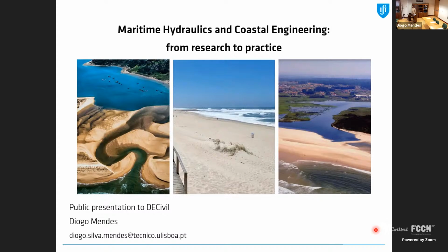Another thing is that you were showing two lagoons, the Albufeira Lagoon and the Barrinha de Esmoriz. But actually one opens, as we were saying, the Barrinha de Esmoriz, and the other one is not able to open to the sea. This is due to different mechanisms happening at the location, because in the smallest one, on the right, you have freshwater accumulation that is enough. Actually, this is a problem because if it is closed and not open to the sea, the people in urban areas start to suffer some kind of inundation. On the second one, this mechanism doesn't happen because you don't have enough stream or river to fill the lagoon and reach the opening to the sea.